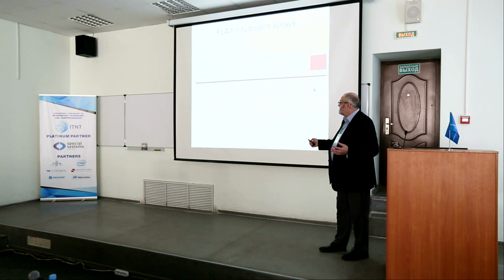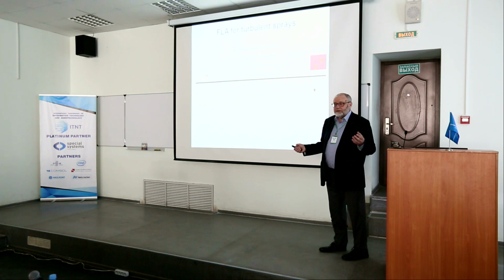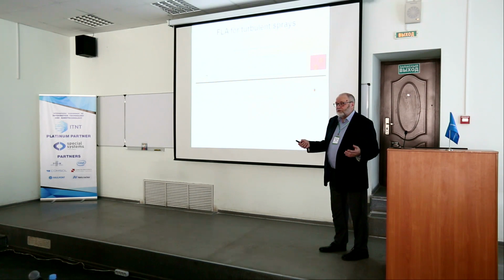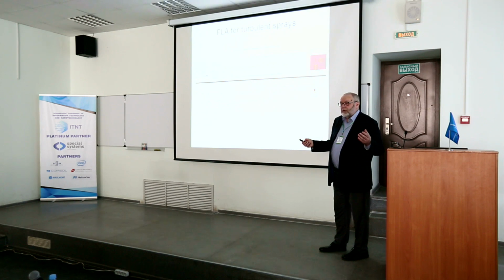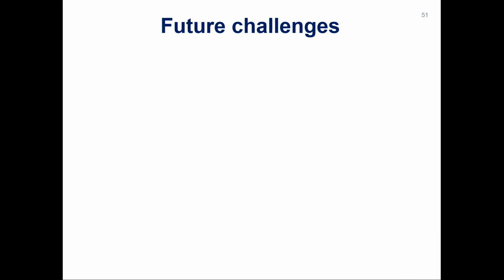it appears to be rather tricky to apply this method to turbulent sprays. Some initial work in this direction was performed mainly by my colleague Andreas Papoutsakis, and we developed a model for the evolution of a droplet cloud in a turbulent flow, but this model is based on a number of rather serious assumptions and limitations, and we are working on a more general model in which these limitations could be dropped.